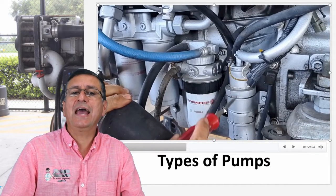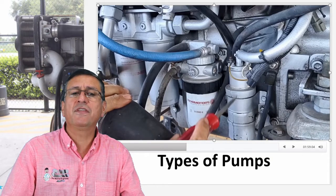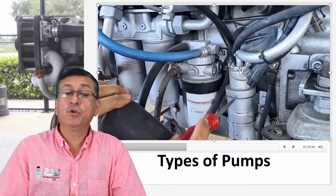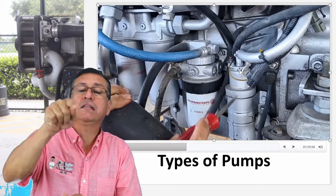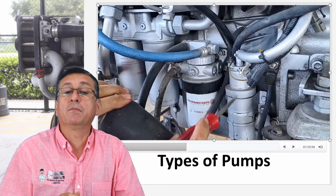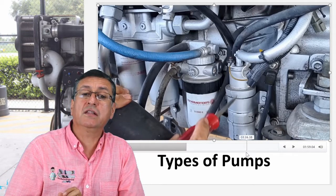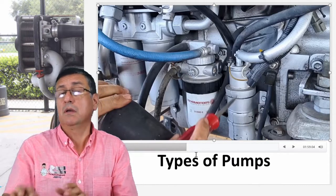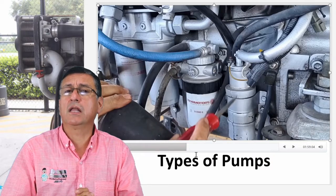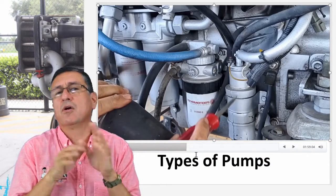Okay, this is the electrical pump or electronic pump. This pump receives the power here and here from the computer. The computer, the ECM of that engine, sends the signal to activate that pump. And that pump receives low pressure here and sends high pressure in the output. It's high pressure because it's around 3000 psi or a little higher. But in terms of a fuel injection system, this is considered low pressure.